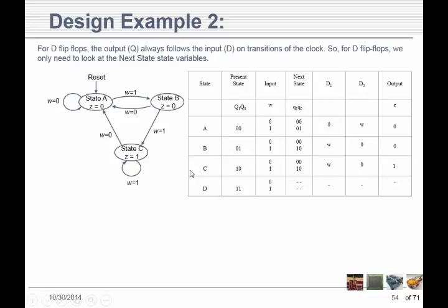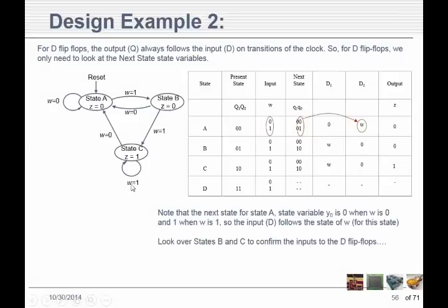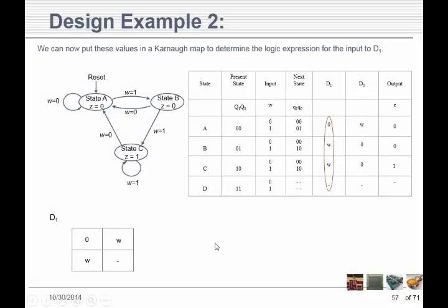And here we finally have C. The output goes high when we're in state C. So when we have 1, 0 here, the output has to go high. So we could take, as a present state, a 1, 0, and basically AND 1 and not 0 together to get a 1 for the output. So you can look through the slides and see how all that works.